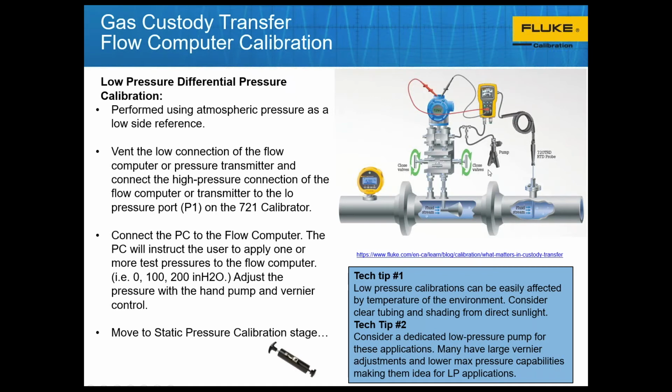So even though they're not expensive, they're still potentially a preferred piece of equipment over this type of pump that is a pneumatic pump, but is intended to work maybe as high as 600 psi. So it sacrifices a bit of that adjustability for the higher pressures. So in these applications, I recommend potentially changing out this pump for that in the image.